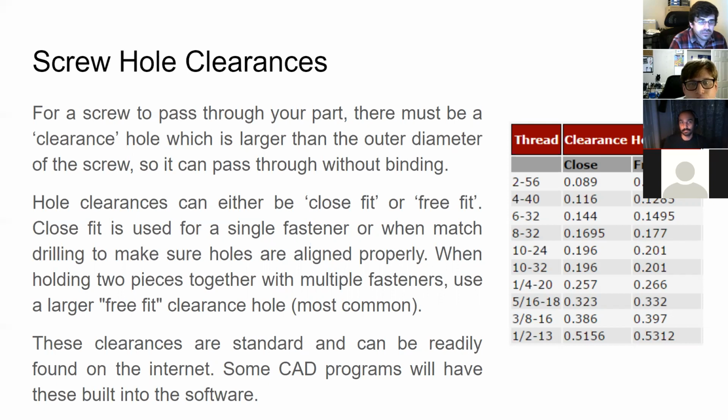So I'll just hop in here and say some quick assembly tips. So you can tell the difference between close fit and free fit because it'll be harder to push a screw into a close fit hole sometimes, especially if you have metal burrs hanging off. Also with assembly, there is a tolerance built in, so you can absolutely misalign two parts, even if the screw is going through a hole in both parts. So you want to be paying attention to that and making sure edges are aligned. Don't just assume, oh, the screw has gone through my parts, therefore they are correct, because that can definitely not be the case. For those of y'all who were at the meeting yesterday when we were assembling the perimeter, y'all got to learn about that firsthand.